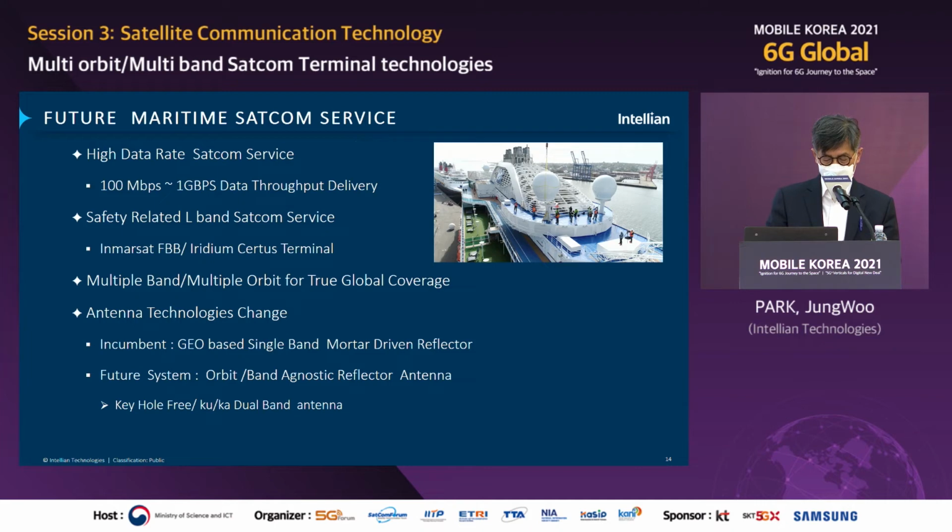So the technology adopted should be multiple orbit tracking capable and Ku, Ka band capable with a single feed system. However, flat panel antenna technology for maritime will be very limited because of high-level throughput requirements and also performance degradation due to severe ship motions.